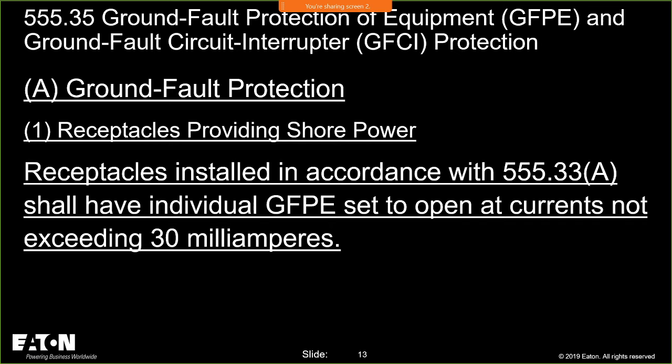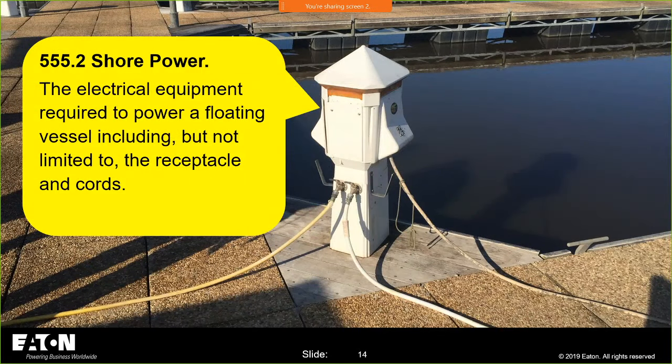And then the point of use, the receptacle outlets that you would be plugging in appliances, 4 to 6 milliamp, your 15, 20 amp circuits. And then anything that's plugging in a boat, we're at 30 milliamps. I think that's a really good solution. So any of the shore power pedestals, those are going to now have 30 milliamps when it's going to power the shore, and it's going to have 4 to 6 milliamps.